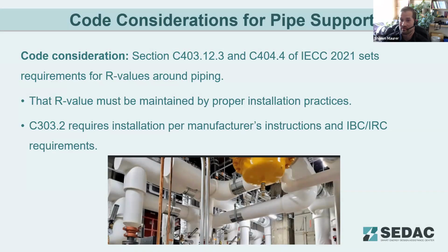The hangers need to be properly adjusted in height so that, once you put water in the system, you're adding a bunch of weight to that pipe, and it can sag down a little bit. We've seen instances where you've got a pipe coming up from the floor on a pump or something, with a 90 going across the ceiling, and the hanger is at the wrong height, where it's actually trying to lift the pipe higher than the elevation of that 90-degree near the ceiling, and that causes crushing of the insulation. So you do have to maintain the proper R-value and thickness to be code compliant.